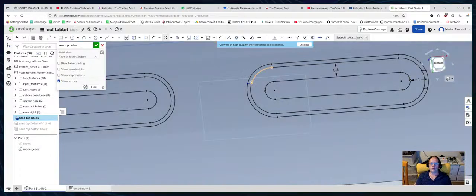Delete it and start again. Trim mode. Draw another rectangle. So it'll be from here out to there, and it's got to be there. Beautiful. Now into trim mode with my scissors. Trim that, trim that, trim that excess thing, trim that. Beautiful. But it's still not constrained. That's really weird. Let's show constraints.